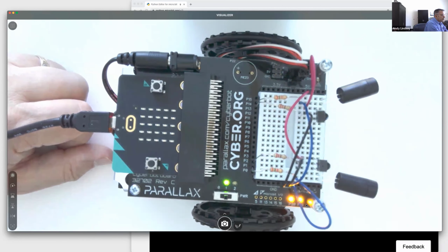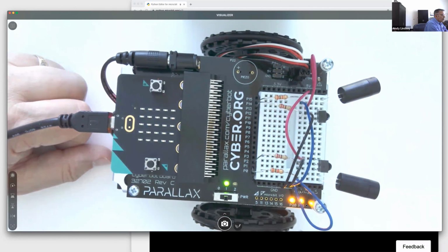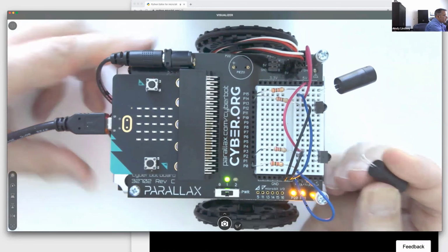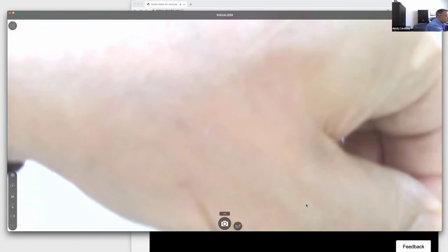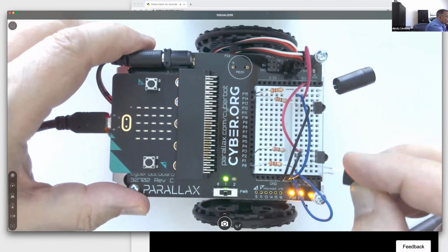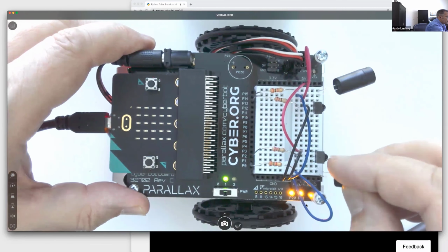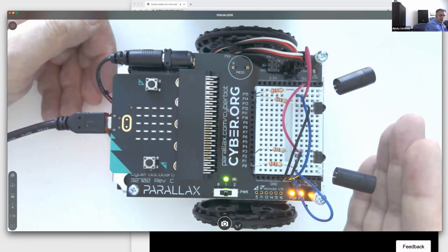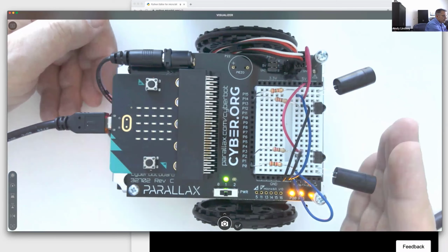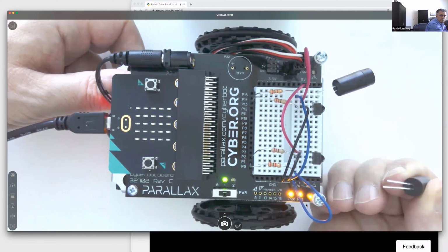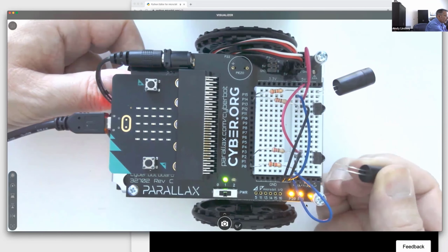And so one reason it would always stay on is if you had this light emitting diode in backwards with the longer pin closer to the black sockets below it. So if I plug it in backwards like that, see how I put my hand in front of it, but the light doesn't go out? So then I check it and, oh, goodness sakes, look at that. The longer pin was in the bottom instead of the top.